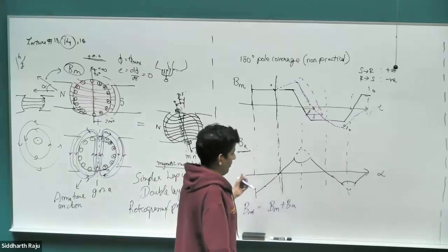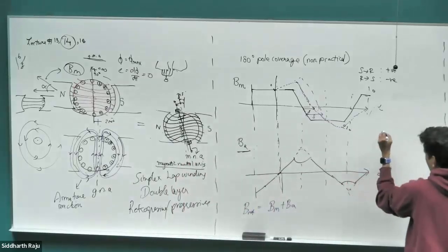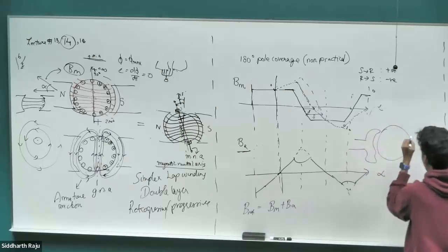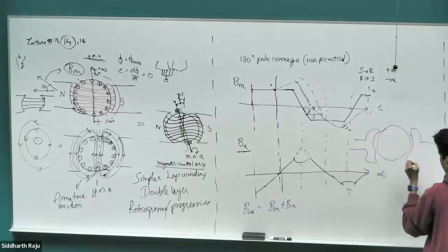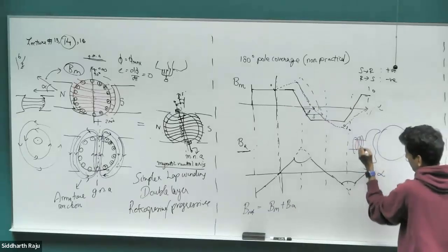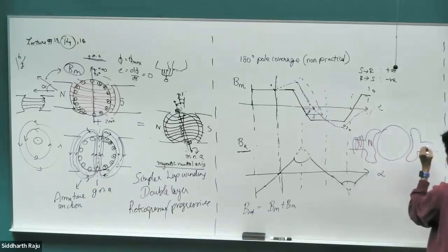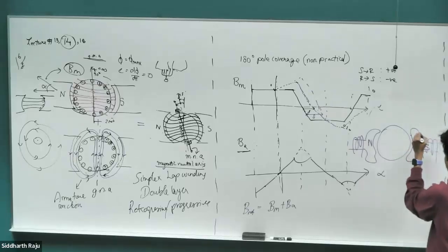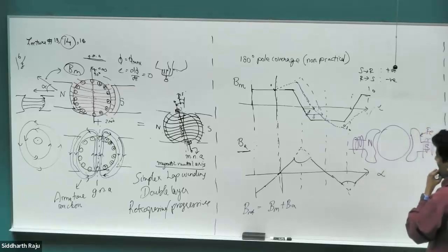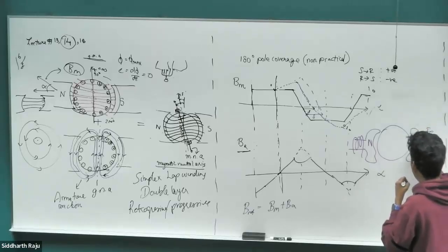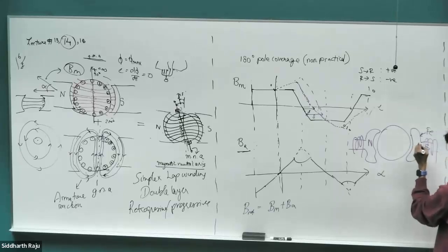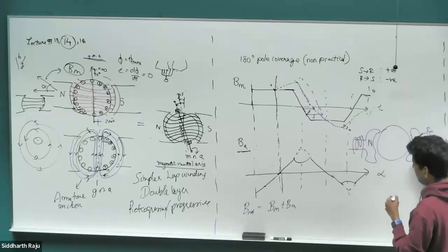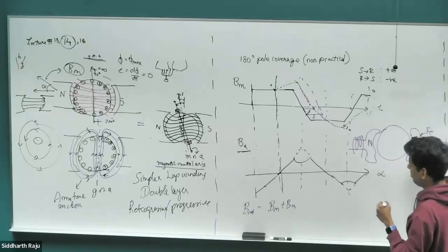So typically you would see the structure in DC motors that are wound field. So you have the structure on which instead of using a magnet, you would basically use a field coil that is creating the electromagnet. Right? And these structures would be again iron. And here the mu r is pretty large. Right? Mu r is close to infinity. So the field lines here particularly makes much more difference whether you have saliency or you don't have saliency.